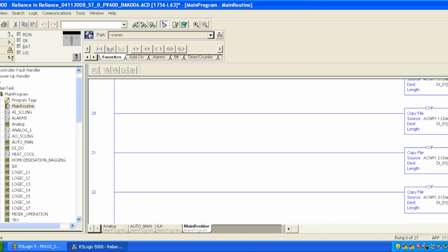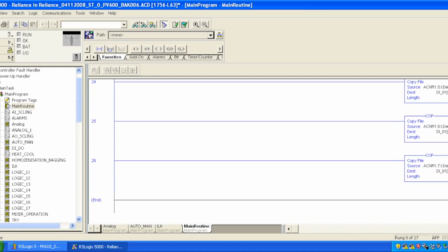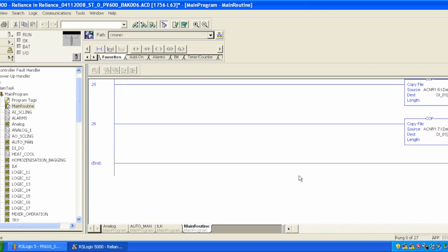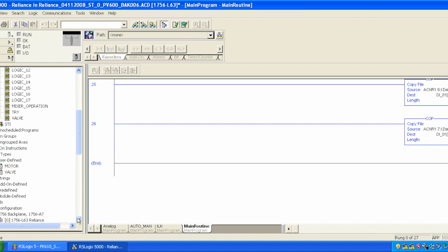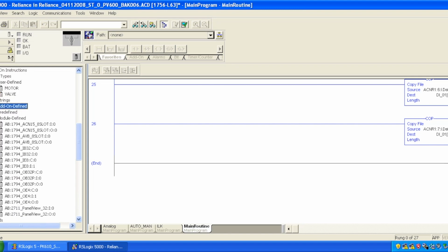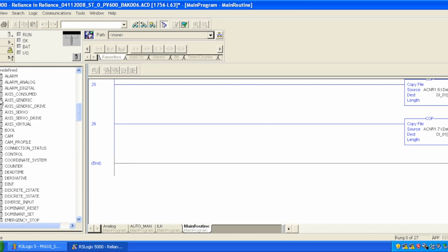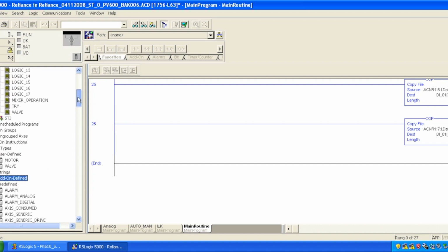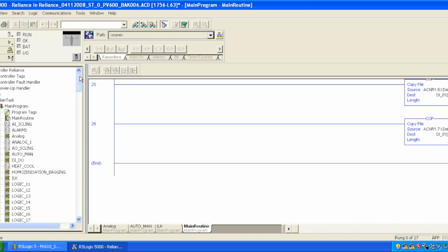The way of programming changed a little from the earlier one, correct? It started supporting creation of new function blocks. There were also predefined functions already present, but we can create our new function blocks as add-on blocks, add-on instructions. In this one, we were also supposed to create our own user-defined data types. Those started being supported, and it was mostly going into the procedural programming part, or somehow object-oriented programming also.